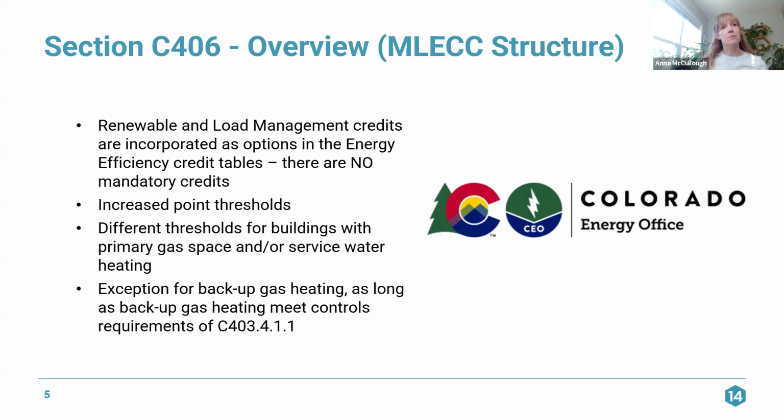There are increased point thresholds required as compared to the points that are required under the 2024 IECC. And then they also have created different point thresholds for buildings with primary gas space and/or service water heating.